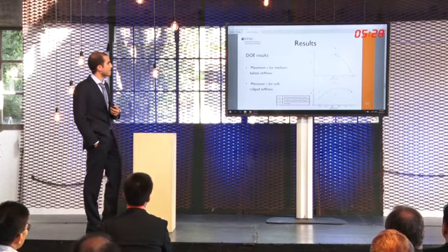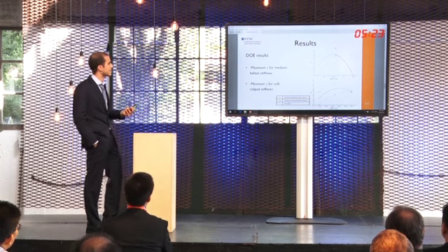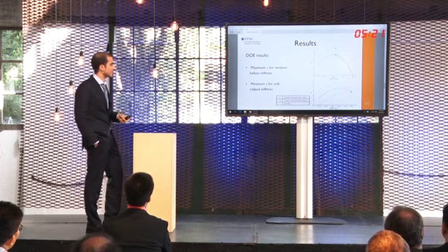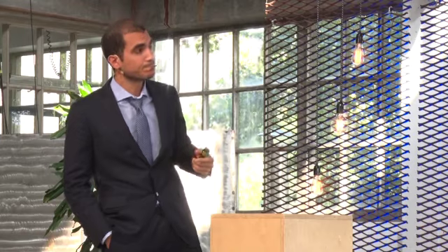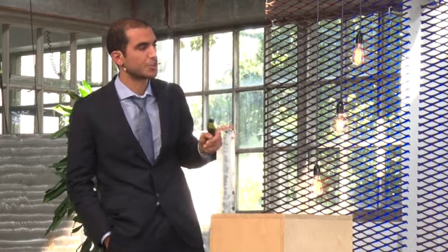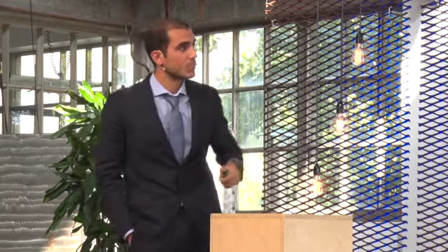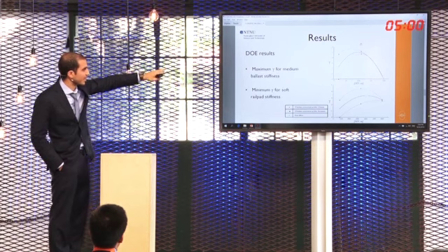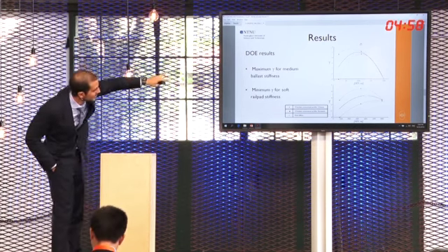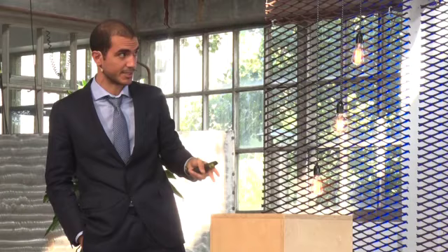All right. Here, we can see the results of the design of experiment or the parameter analysis for what regards the three-level factors. On the top, we can see the effect of the vertical ballast stiffness, and on the bottom, the effect of the vertical pad stiffness, in terms of the main effect with the solid line, and with the other lines the combination effect with respect to the wheel-set transversal profiles.